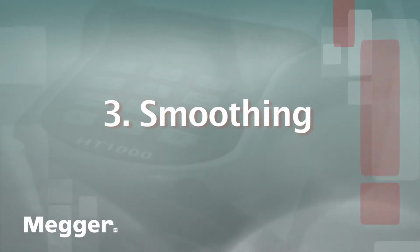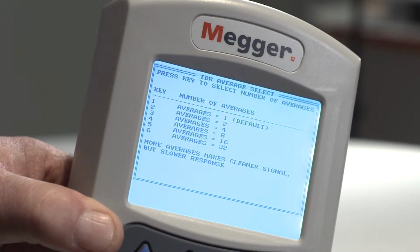3. Smoothing opens the TDR averages list. Press the corresponding key on the alphanumeric keypad to select. More averaging smooths out the presence of line noise displayed on the waveform, providing a cleaner signal, but slows the display response. The default filter level is 1.